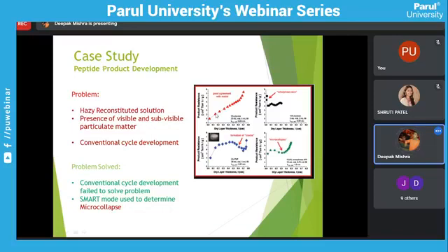The second one is formation of cracks. If you have seen any lyophilized product previously, you can see cracks in the drug product. SMART Lyo technology can determine how these cracks form. We check on the basis of dry layer thickness and product resistance, so crack generation in the lyo cake is also found out by this technology.